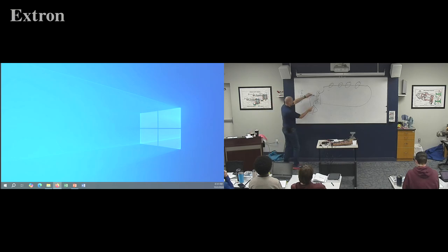Steven, what voltage would I get if I put my voltmeter from this terminal to this terminal if it's hooked up that way? 12, yeah. Cool. What if I go from this terminal to this terminal? Timothy Peak? 0. 0, because I'm not dropping anywhere, it's just connected with a wire. What if I go from this terminal to that terminal?